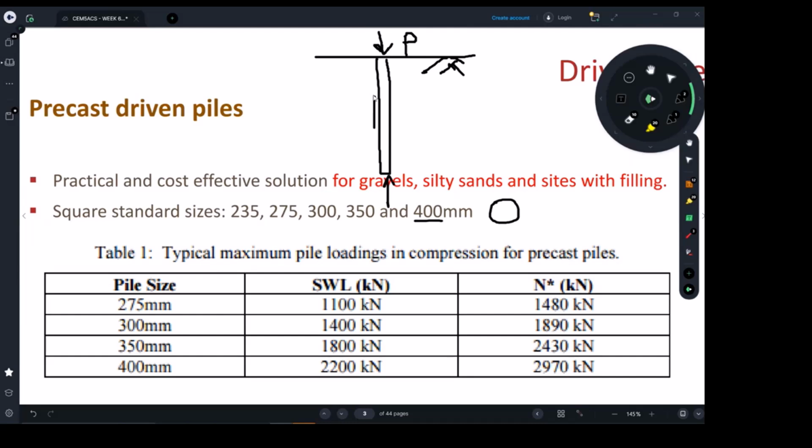So what else do we use? We use the skin friction. The skin friction that I'm showing you is another important component for us to use and calculate the total P. So here we've got PA and also PB, let's call it. How it really works is the engineers calculate the addition of both components together, reduced by a safety factor, and make sure it's more than or equal to whatever force is going to be applied.